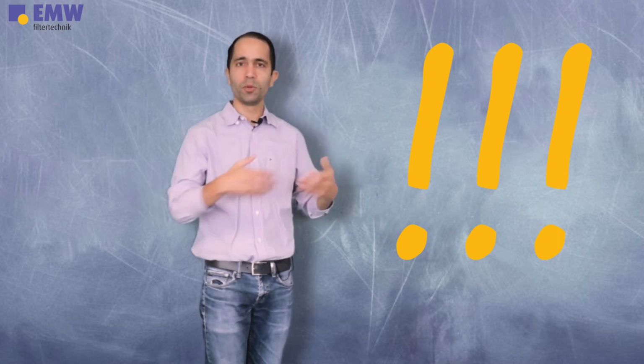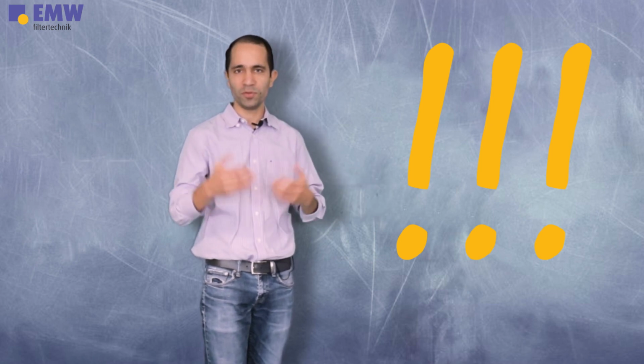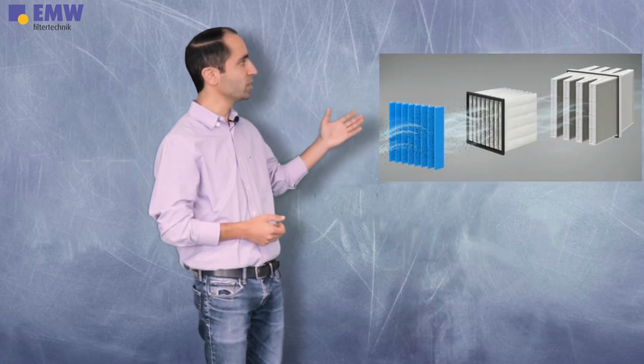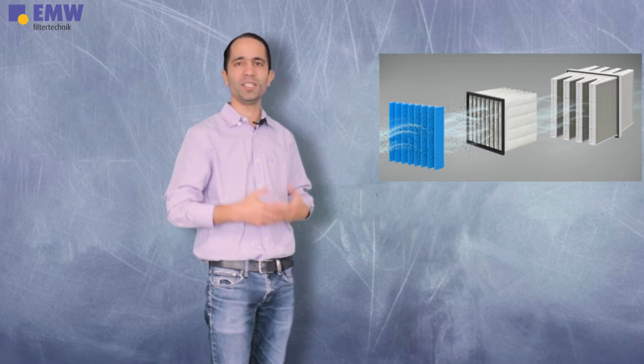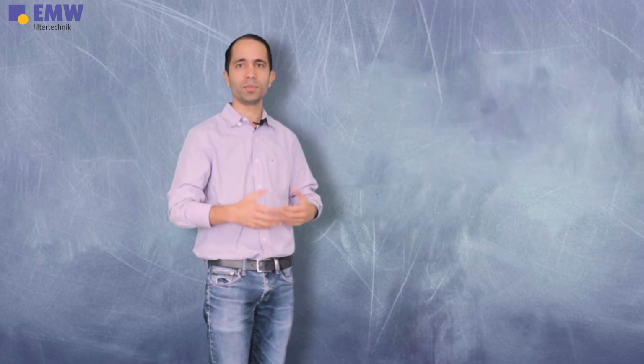However, you really have to be critical of certain test data you compare, or which got achieved on a test rig, in comparison to the results which you would achieve in real ambient conditions. For example, the dust holding capacity of the filter classes T10 to T13, which are comparable with the EPA and HEPA filter classes, is not really worth a deeper look, because from my experience you would always have to consider a good arrangement of pre-filters upfront of such a highly efficient filter device, and the pre-filters really gain weight by capturing the large rough particles.